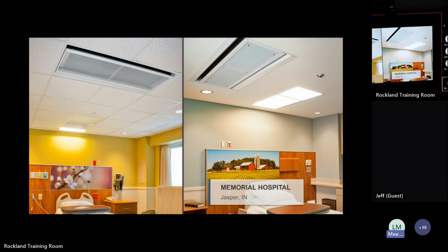Next up is healthcare. Is anybody working on healthcare projects at this point? Okay. So chilled beams with healthcare, there are some allowable spaces. It's actually a more recent ASHRAE 170 publication that allowed, in the addendum, the recirculation component of the chilled beam. It's been in the addendum a while, or a part of the standards, but now it's been moved into the main body of the ASHRAE 170 for recirculation units in the space, and whether you need filters in the chilled beams or not. So that's a really critical item to look at.